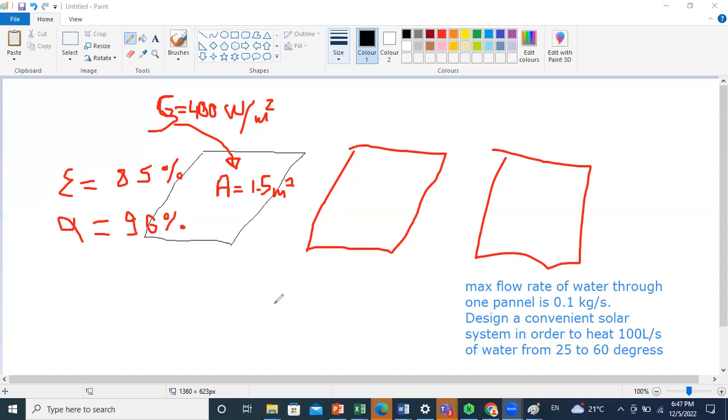To be on the safe side and account for possible losses, let us use 8. But in the problem, if they don't specify any safety factor, or they don't say what is the value of losses, you can work without losses. In general, engineers at the end, when they do a design, will take a certain safety factor into account in order to consider all things that were neglected in the analysis.